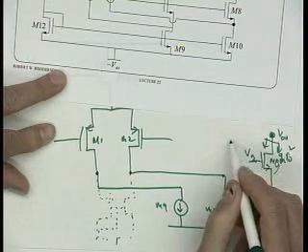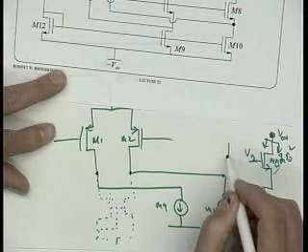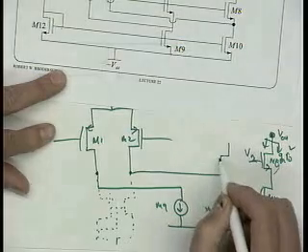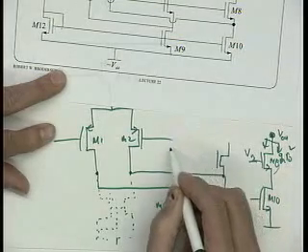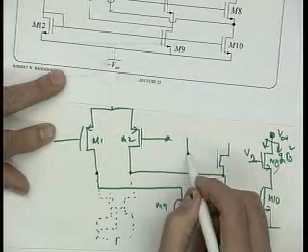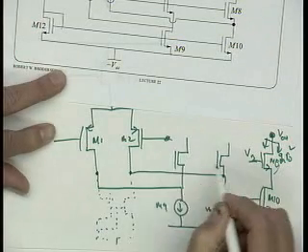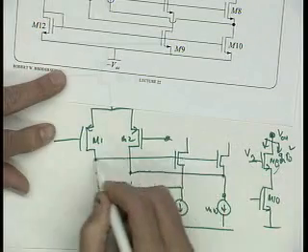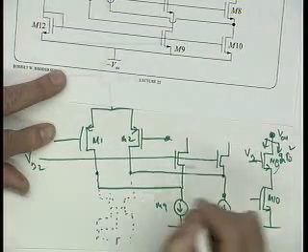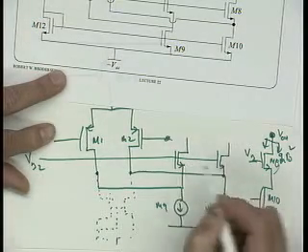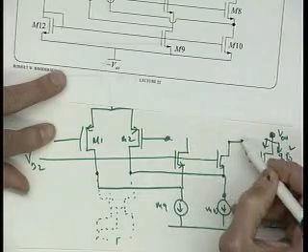Okay? So let's put that in there. So we just know what we got here. It's just a cascode device. And I'll put another one over here for symmetry. The second one's for symmetry. This goes off to a bias, V bias 2. Okay? Here we're taking our output.